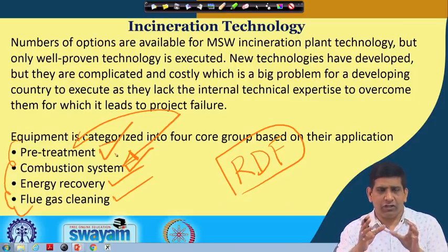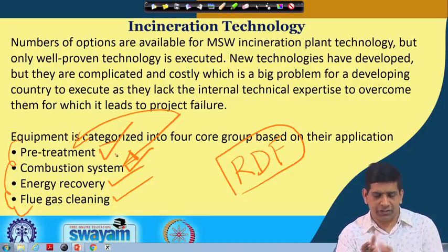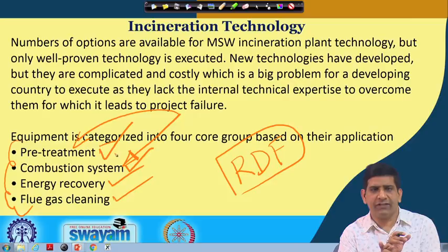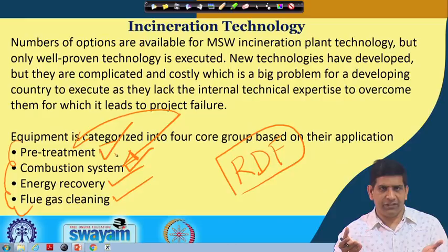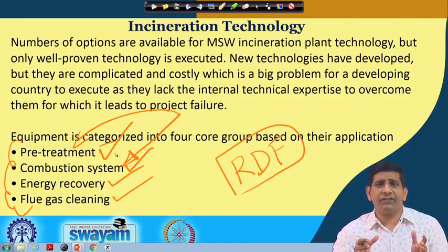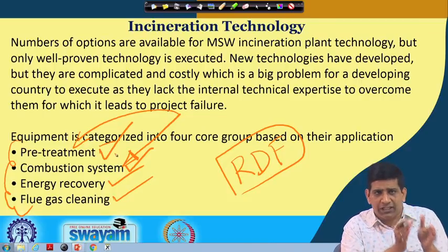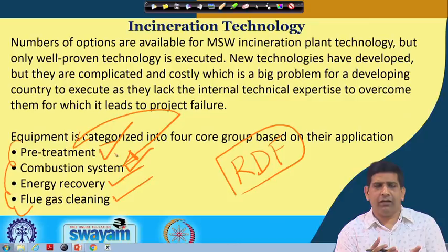Here we are just talking about how plastic waste can be managed using incineration technology. So you will take all those hazardous things out and make the moisture content low, or if you are going to use RDF, you will shred it, and rather than using a mass burn facility, you will use an RDF facility, which increases the efficiency of the system. But then again, you need to put the earlier systems in place to make RDF, which has a cost as well.